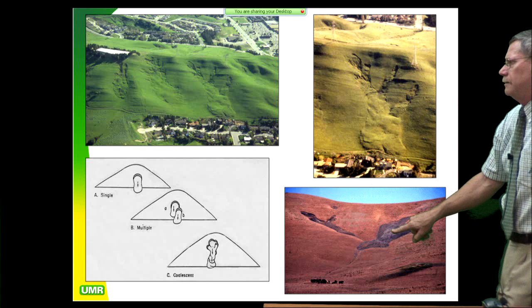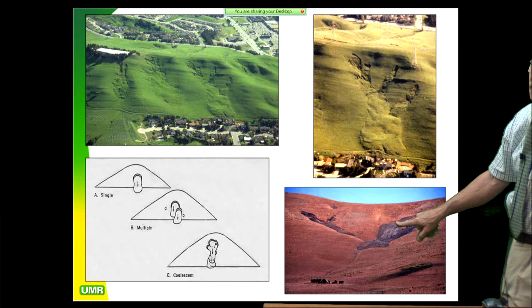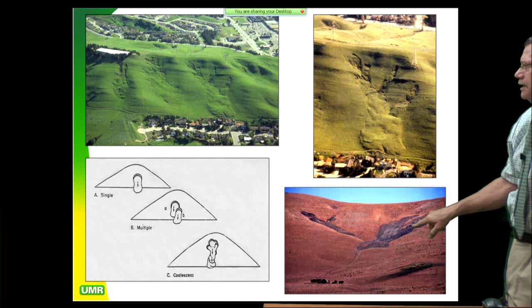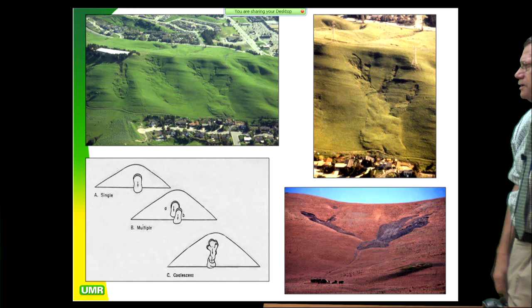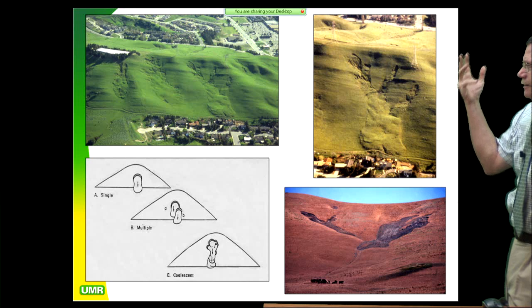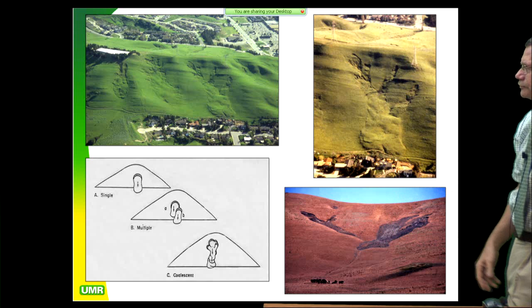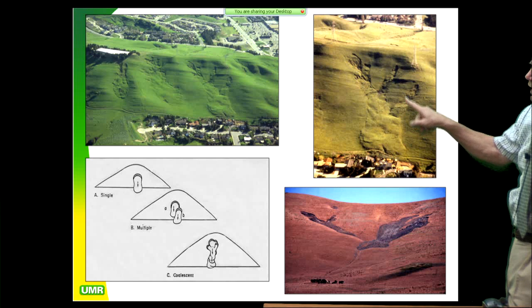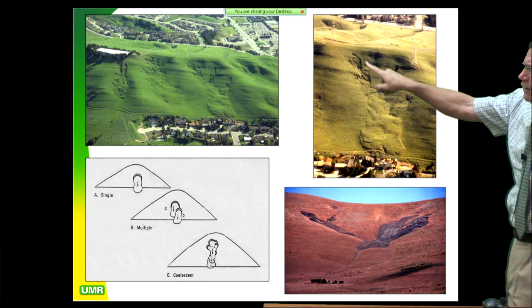Now this is all fat clay above the A-line. Fat clay above the A-line isn't supposed to be flowing around with no shear strength. It's got cohesion. It's got intrinsic strength. How can it be doing that? Well, real easy. High pore pressures. See right here? Blowout, blowout, blowout, blowout.